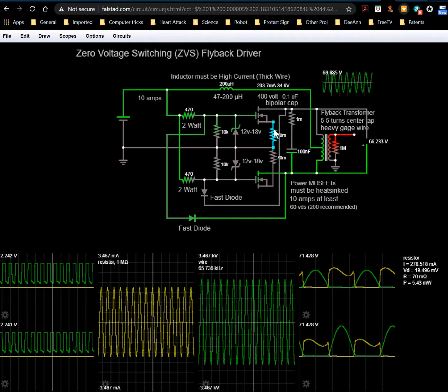It wouldn't matter. In fact, theoretically, you could get rid of these diodes and drive this with a 555 timer, maybe a 555 timer and an inverter, for example, taking into account sticking it through some resistors so you can get it up to 12 volts. But theoretically you could drive this and have this one go on when the pulse is high, and this one go on when the pulse is low. Again, this one goes direct from the 555, and this goes through a CMOS inverter with a transistor on it, that kind of thing. But you'll probably need some drive circuitry because of the currents involved.